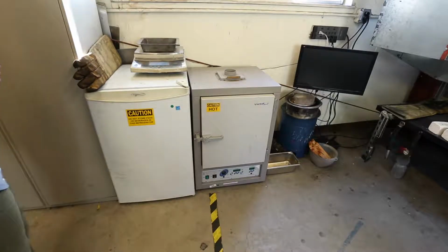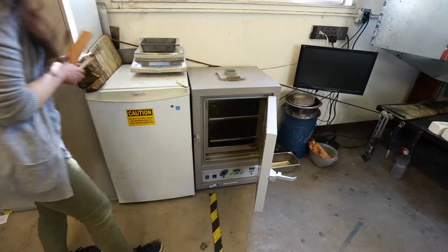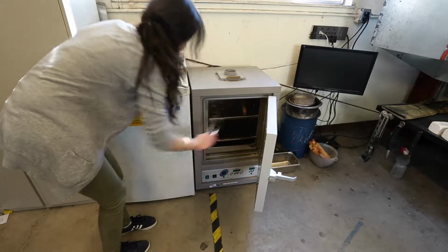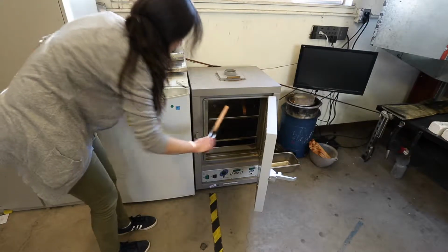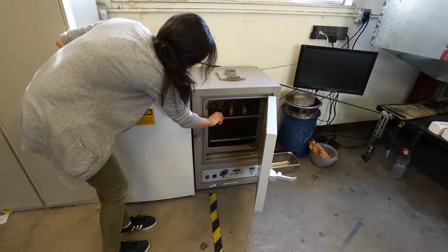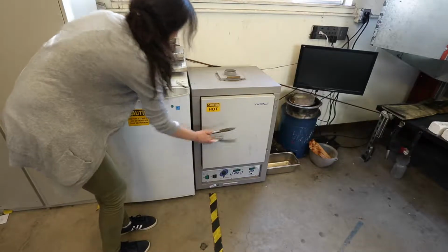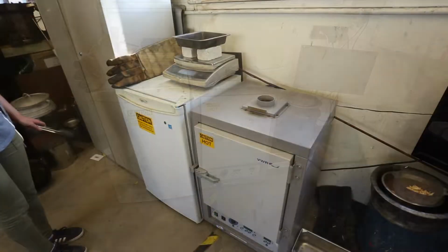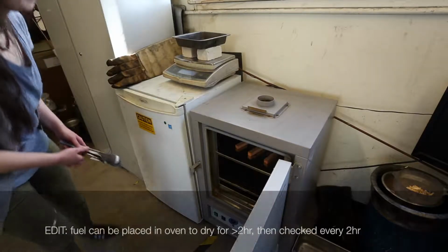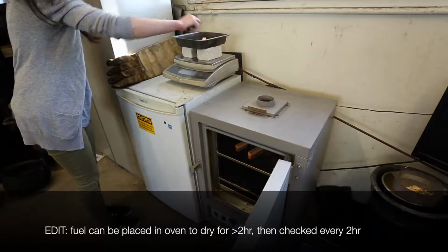The moisture content of fuels is measured via the oven dry method. This method compares the mass of fuel before and after unbound water has been evaporated in an oven. Your lab should use a laboratory-grade oven capable of maintaining a stable temperature of approximately 103 degrees Celsius for many hours. To ensure all water has been evaporated, the fuel sample is removed from the oven and weighed every 2 hours until consecutive weighings either do not differ, or rather differ within a predetermined acceptable error.